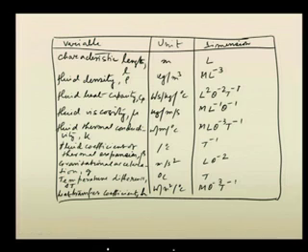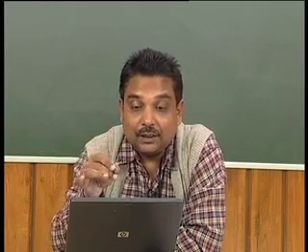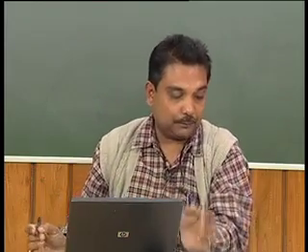Now, what we have to do is write down the equation in the form of dimensions for the different dimensionless groups, and then, by analyzing the dimensions, we have to find out the values of all the coefficients that we have listed down. Okay. So, if we see for pi 1, it is pi 1 equals L to the power A1, then mu to the power B1, then k to the power C1, beta to the power D1 and Cp.